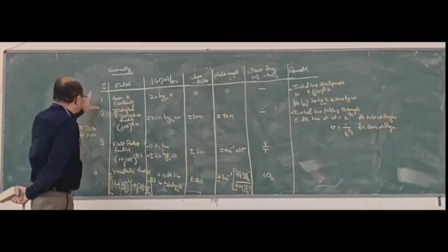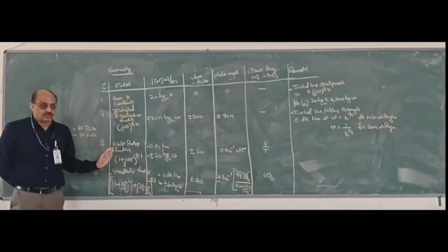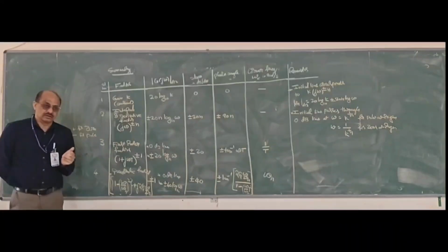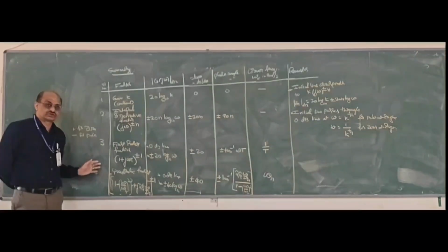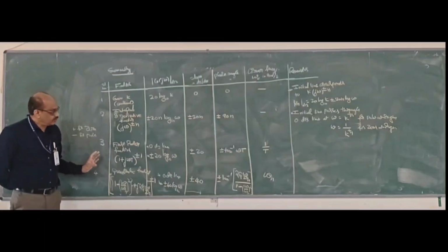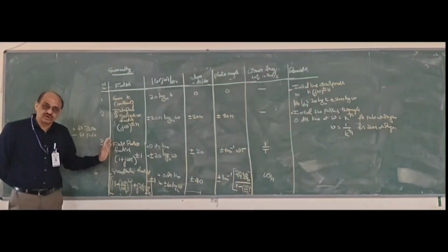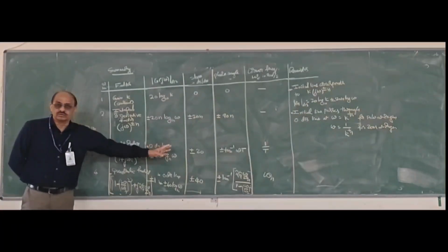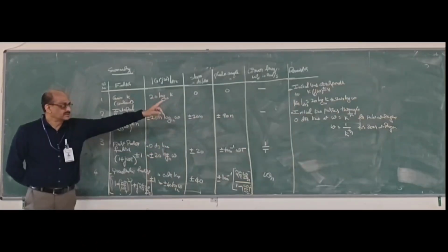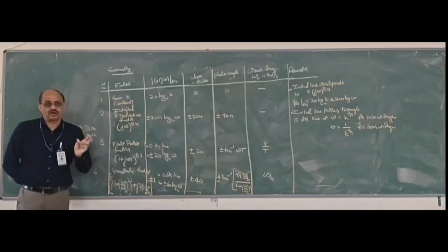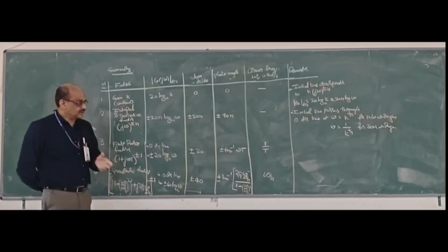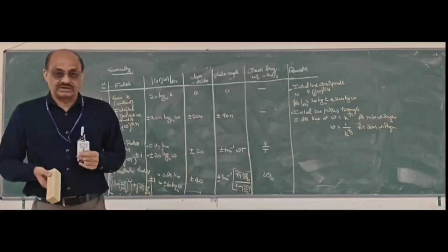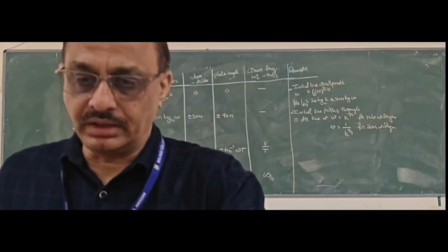Yes, so as I told, whatever discussions we had over 3 hours at a stretch culminate into one simple summary. For a sketch, you need to remember only this. Important is the slope, the corner frequency, and what the initial line is. If you learn that much, you can sketch the entire Bode plot for any given transfer function.